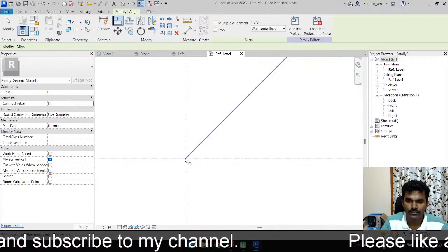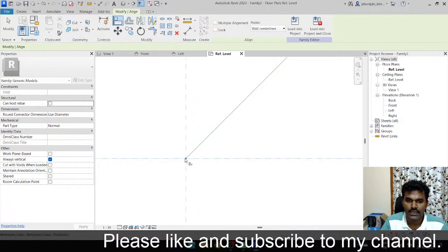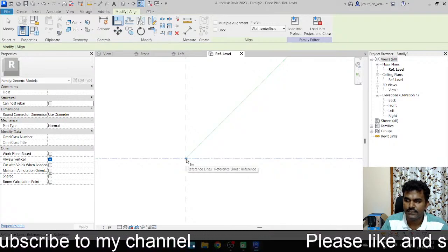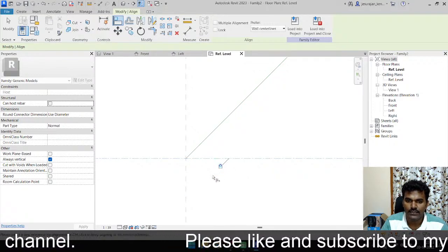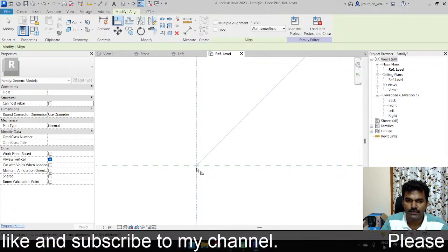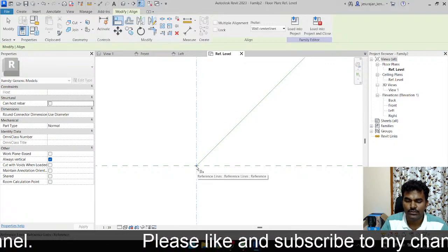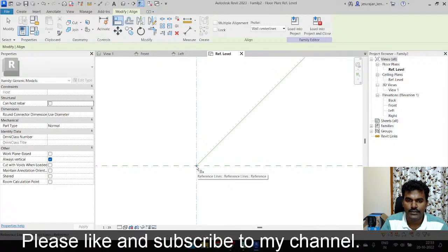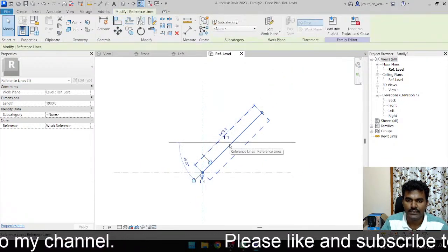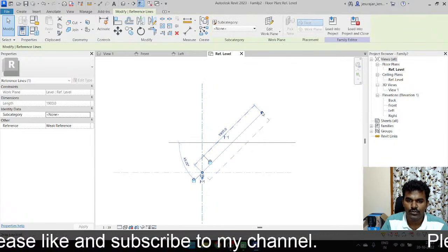See here, I'm pressing Tab to select the point. I think this point is visible to you. If you can see, it's a point. I'm selecting and locking it. We have to do the same with the vertical reference plane. Select the reference plane and select the line. I have to press Tab so that it can select the point. I'm selecting the point and locking it. Now you see, this first point is locked and the second point is free.